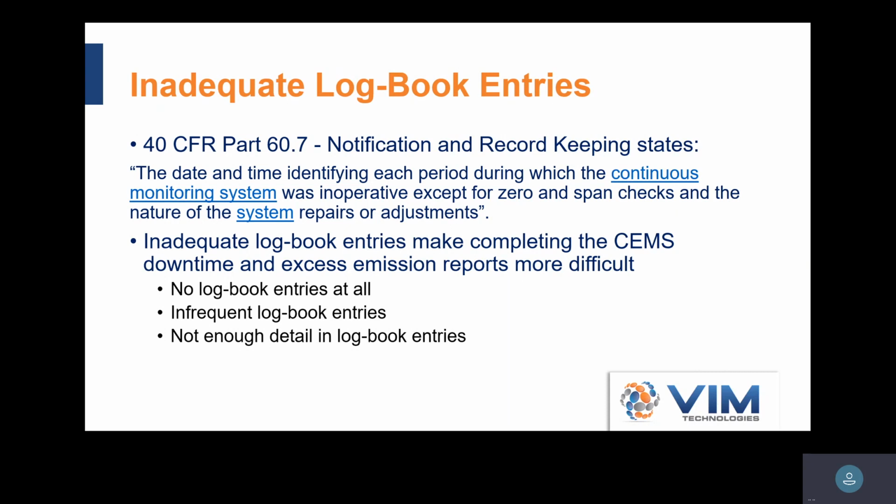When I first started as a tech at the first refinery I worked at, my boss had us write a paragraph for every entry, which was a little over and above. I'm not recommending you do that, but once I became manager, it was very important to get the necessary information in there. So we would always put date, time, person, and then the nature of the visit, if you will. Just a visual check, everything okay, or sample pump not functioning properly, rebuilt sample pump, stuff into that line, so that when I had to go collect the 28 logbooks from the different units, I could properly assemble the reports.